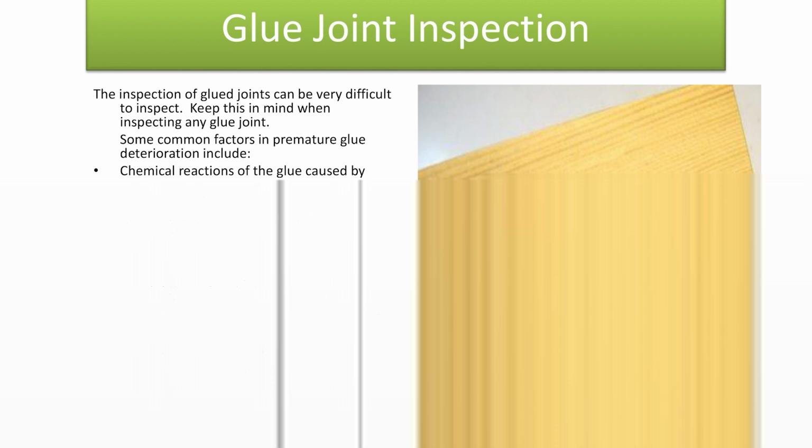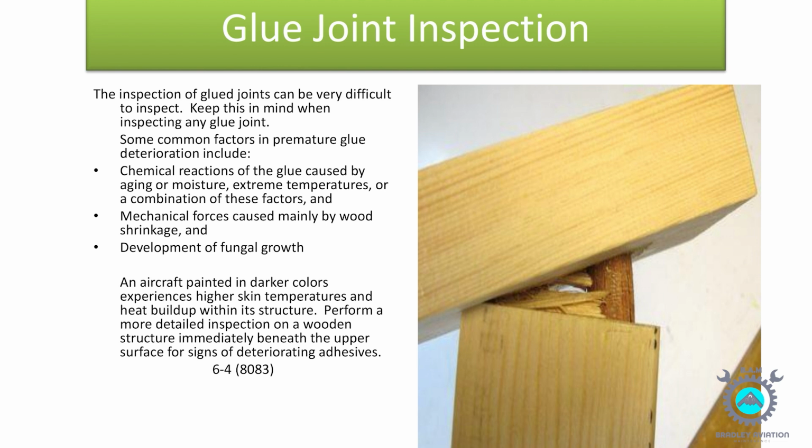An aircraft painted in darker colors experiences higher skin temperatures and heat buildup within its structure. Perform a more detailed inspection on a wooden structure immediately beneath the upper surface for signs of deteriorating adhesives.